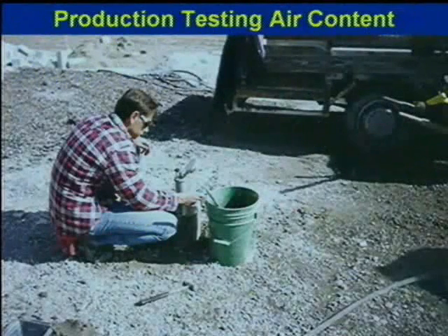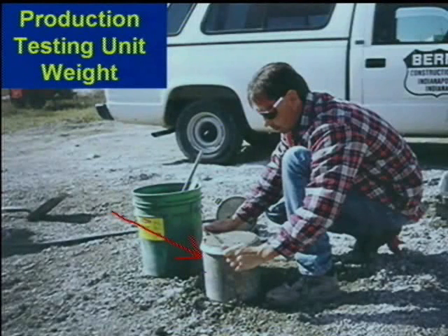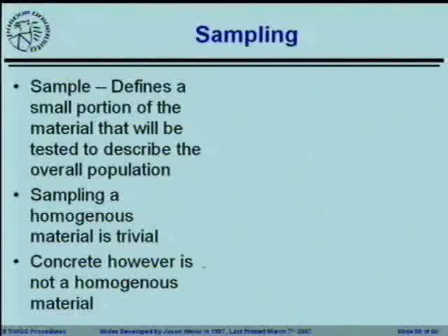Right? Again, usually you're going to take the same concrete and you're going to do the air test. The one thing that I would point out is you could use this simple unit weight type approach using the air meter. It's almost free to do this because all you have to do is weigh the bucket. You're going to do the air test anyway. It's almost free to go ahead and do it.